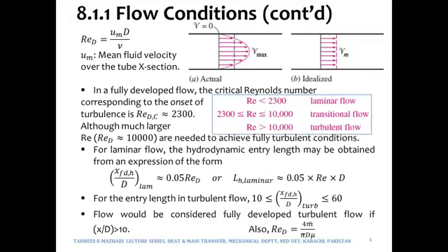And what is the concept of mean velocity? It is the mean of different values of the velocities which occur inside a pipe, ranging from 0 to maximum velocity at the center line. Now, when we consider the flow through a pipe, the critical Reynolds number is said to be 2300.